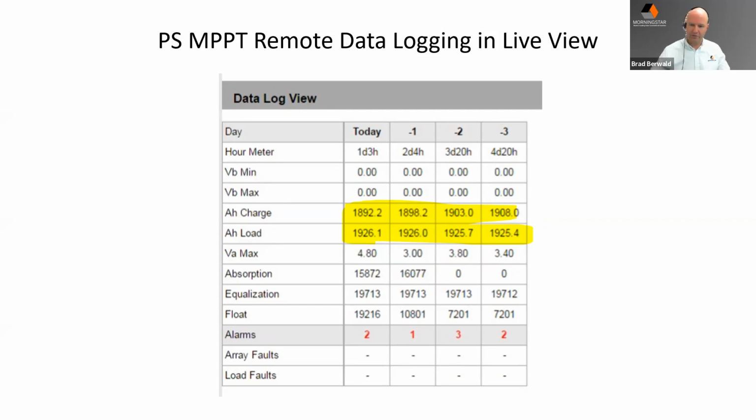And over a longer period of time, several months, this is the first example of where you can start to glean a battery that is just starting to lose its life slowly. Batteries usually don't die instantaneously. They kind of just degrade, and then one day the floor drops out and you notice that your loads start failing on a regular basis. And you can anticipate that and see it coming if you know what to look for in a lot of the data logging files.